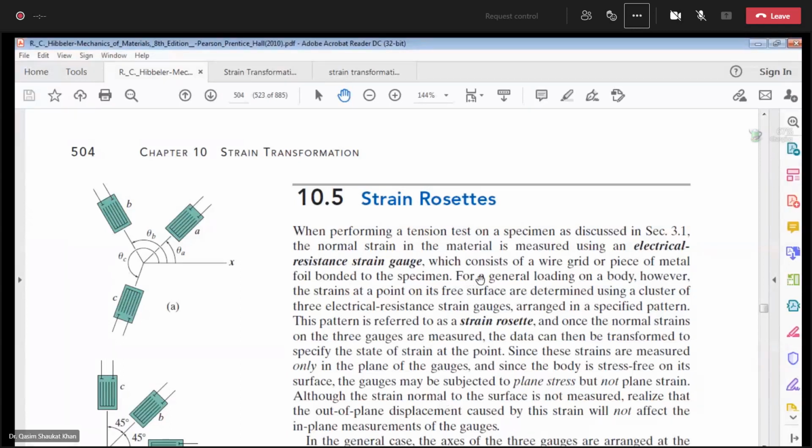About this data acquisition system, when you come here on campus for the lab, I will show you how to attach the strain gauges and how to work with them. It's very simple, but these strain gauges can only be fixed on one surface. Once fixed, they cannot be reused or reattached. In the assembly we made in the lab, we have fixed strain gauges on steel beams. We do not detach them or put them on a new surface; every year we just use them where they are.